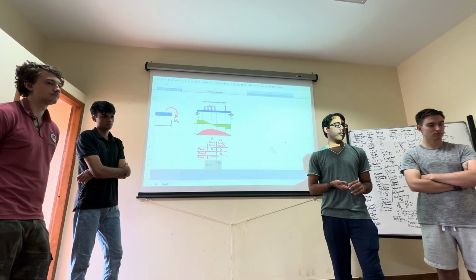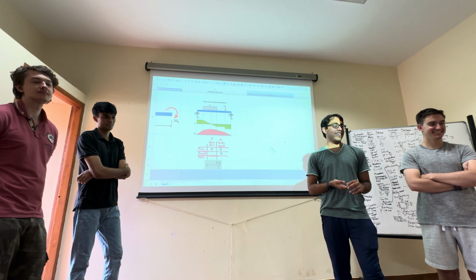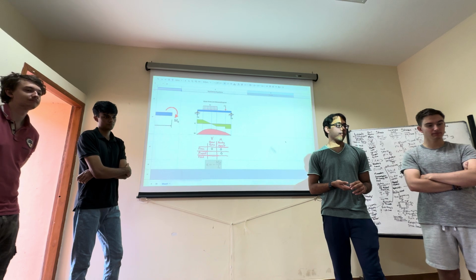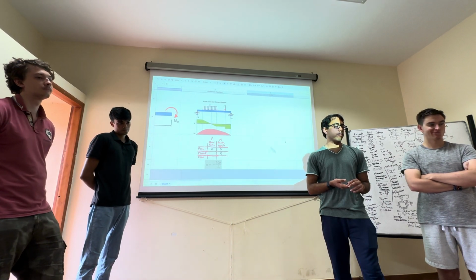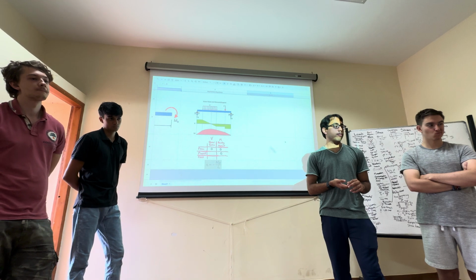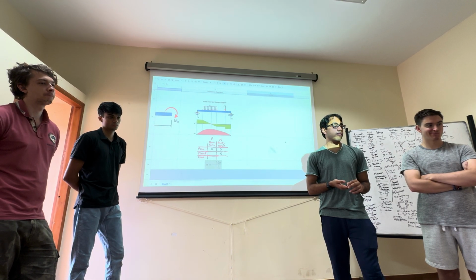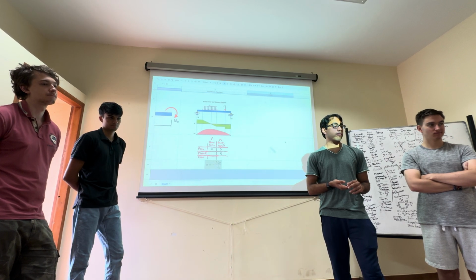Similarly, if I'm hinging it, I can only say that the displacement is 0. So only the displacement is 0. But the hinge is a very interesting case where you can have one natural boundary condition and one geometric boundary condition. The natural boundary condition is that the moment is 0, because it's free to rotate about the hinge.